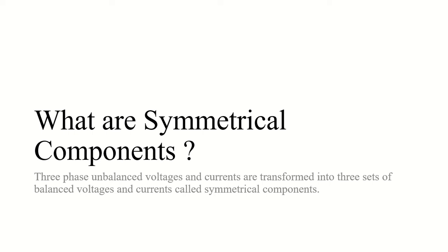There is a more convenient method which we can use for analysis of unbalanced faults, and we call that method the symmetrical component method. Now, what is a symmetrical component? In this method, the three phase unbalanced voltages and currents are transformed into three different sets of balanced voltages and currents, and we call those components symmetrical components.